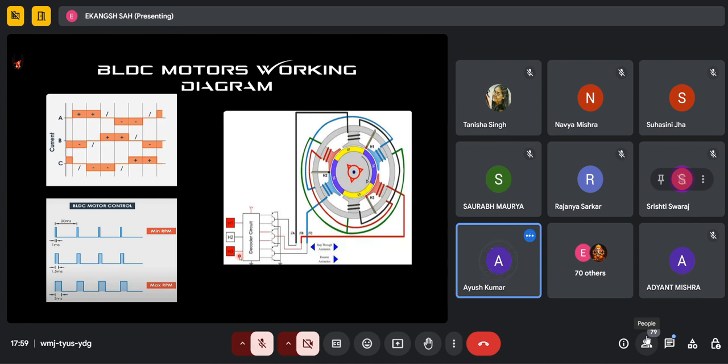The rotor part has a permanent magnet, north-south, which is represented, and with the help of its magnetic field the sensors send data to the ESC, which is in the decoder circuit. With the magnetic field data, it predicts the position of the rotor, and it tells the field effect transistors, which are commanded by the microcontroller of the ESC, which switch has to be turned on in order to decide the path of the current in the three pairs of the motor windings.